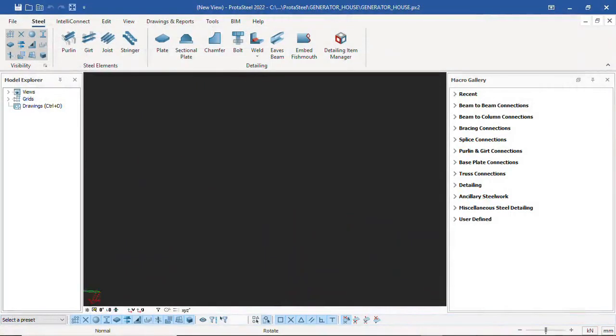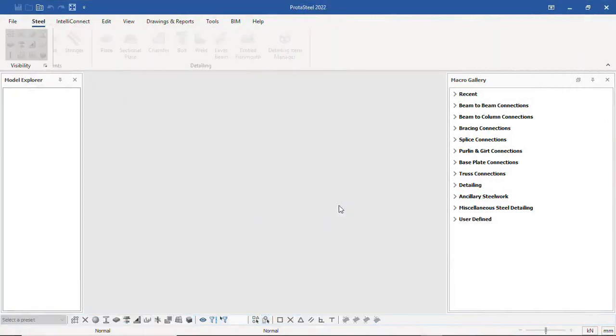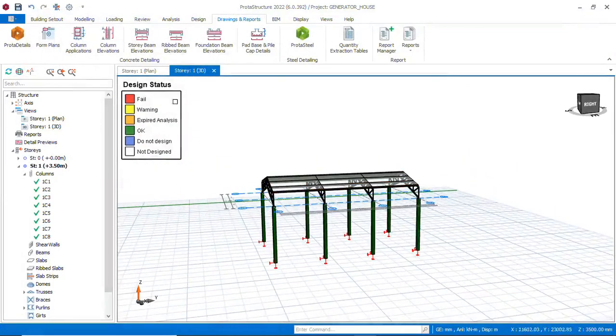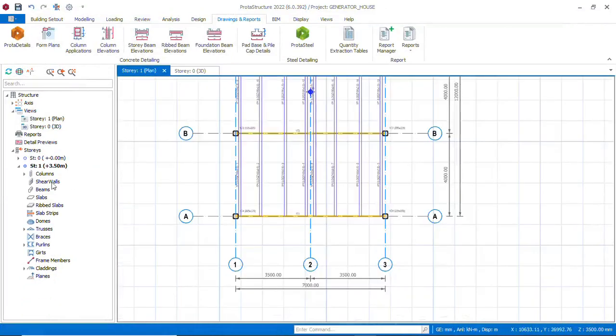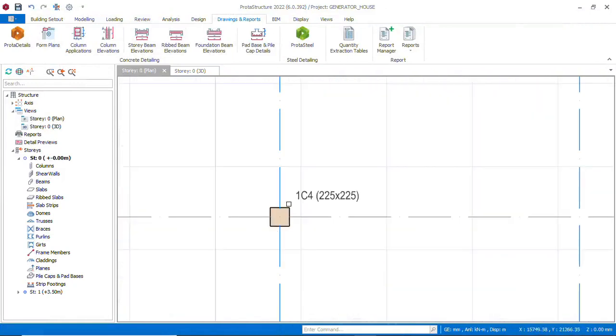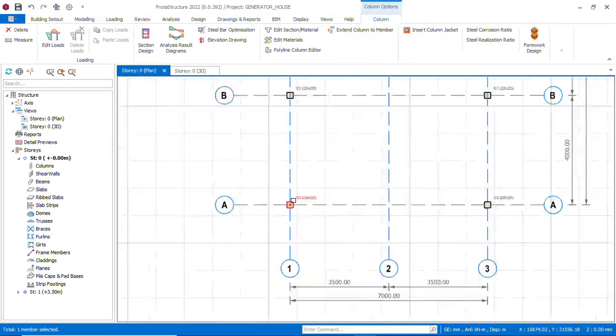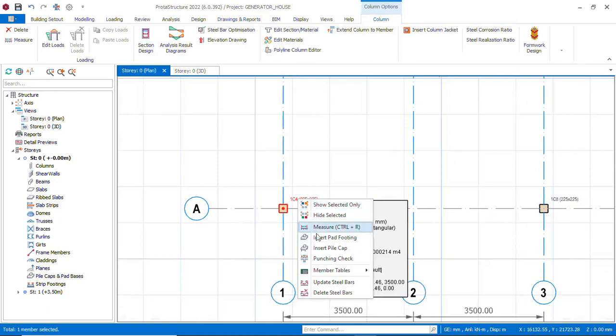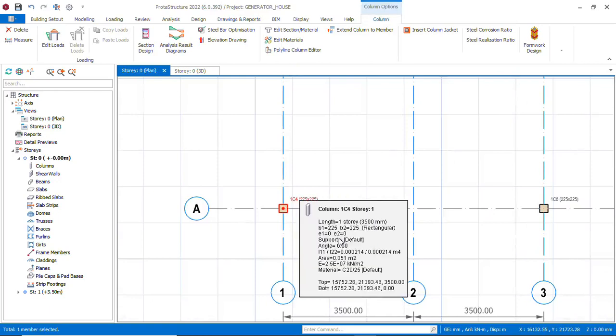See, your Prota is still open just like this, but I'm going to close it. So let me put my foundation. Go to foundation 0, go to level 00, foundation 00, and you can now select all your columns. I will input it once, but the right thing to do is try to insert it one by one if you have time.